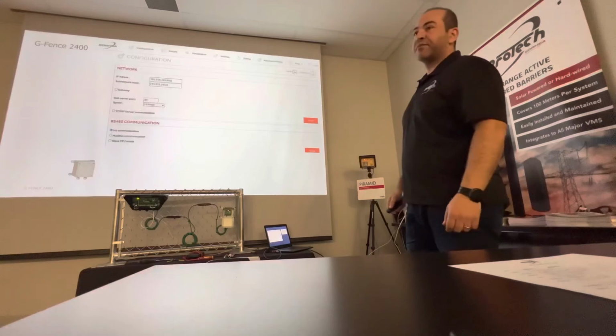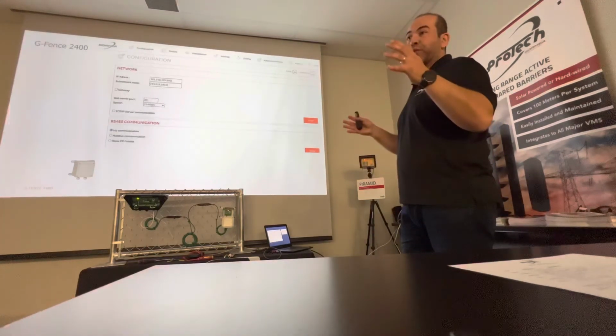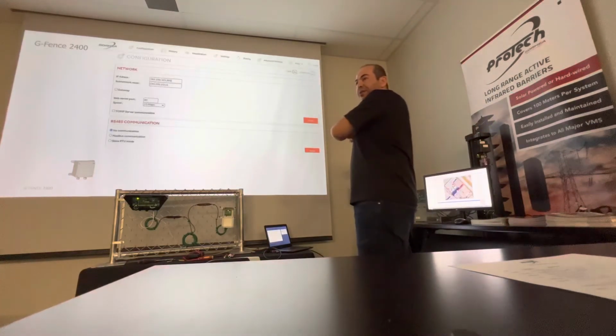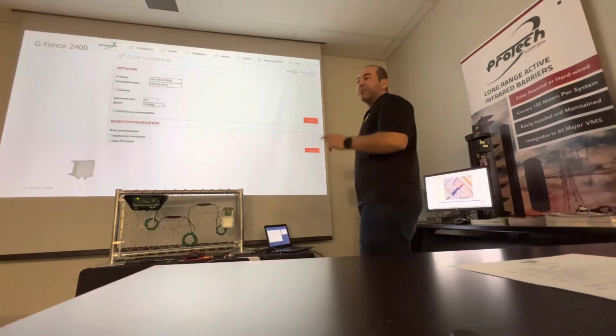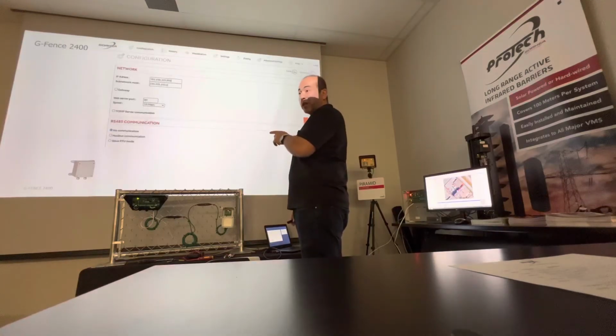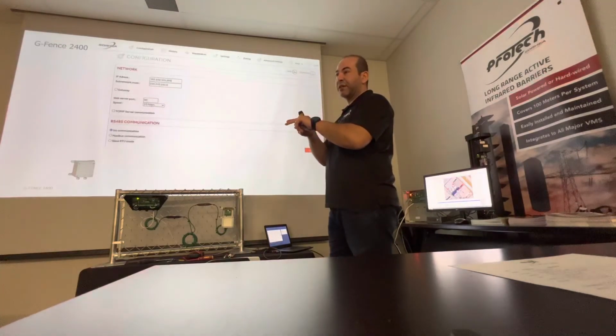You would test each sensor? I mean, usually we test the zone itself. So when it creates zones, we hit the fence a couple of times and we check the logs. We pass through all zones, because usually when you hit the fence, the sensor number, let's say 12, zone number 1, you don't have the choice. It passes through sensor number 1, so if you have a bad sensor on sensor number 1, you will not get the alarms.